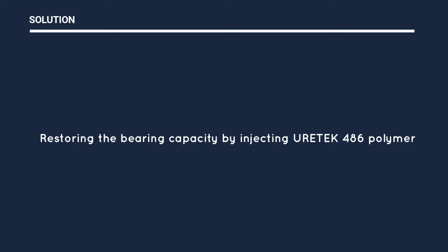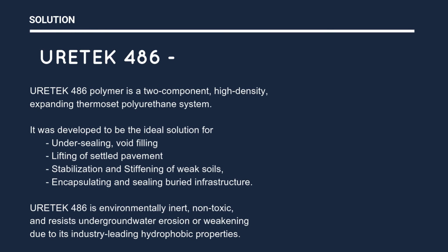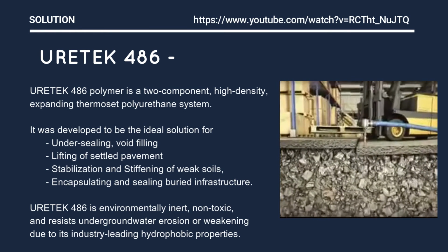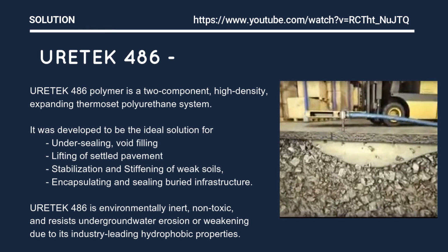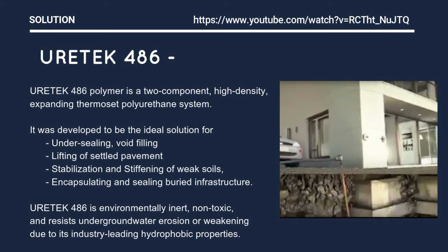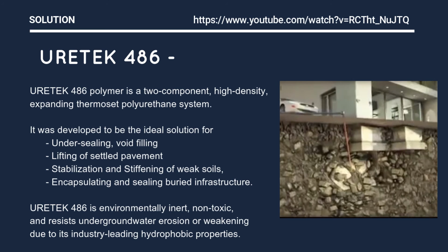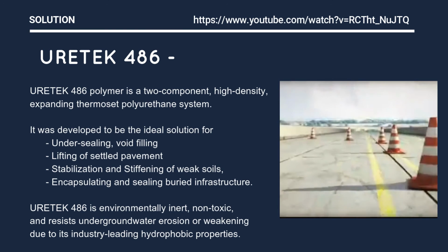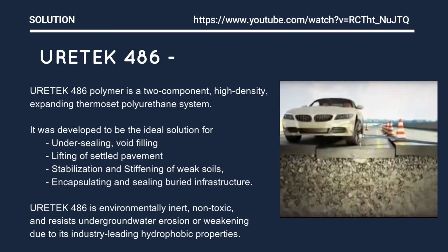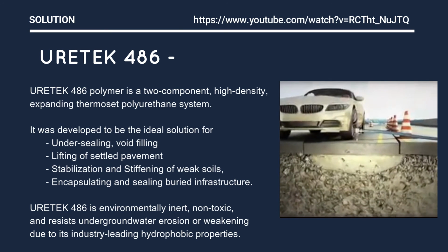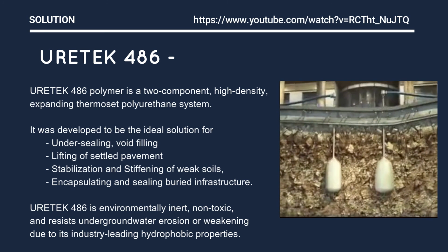Restoring the bearing capacity by injecting this polymer. This polymer is a two-component, high-density, expanding thermoset polyurethane system. It was developed to be the ideal solution for void filling, lifting of settled pavement, stabilization and stiffening of weak soils, and encapsulating and sealing buried infrastructure. It is environmentally inert, non-toxic, and resists underground water erosion or weakening due to its industry-leading hydrophobic properties.